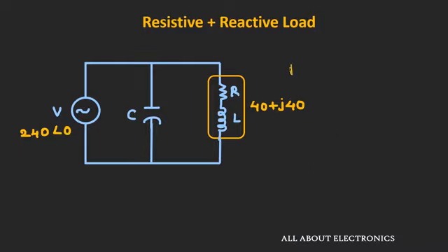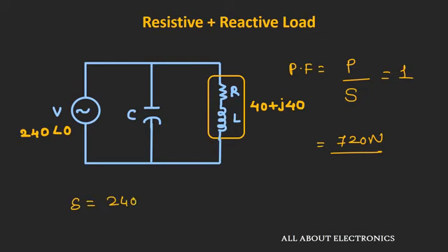And now if you see the power factor PF, that is the ratio of true power divided by the apparent power, it will indeed equal to 1, because earlier we had found that value of this true power is 720 watt and the value of apparent power S, that is equal to 240 volt and 3 ampere current, that will be equal to 720 volt ampere. So in this way, now the power factor will be equal to unity. So now whatever amount of power which is being drawn from the supply will be actually utilized in converting the useful work. So in this way, adding the capacitor, we can improve the power factor of any system.